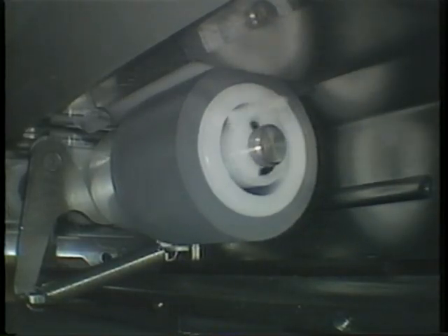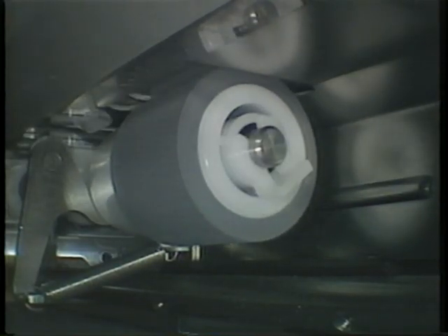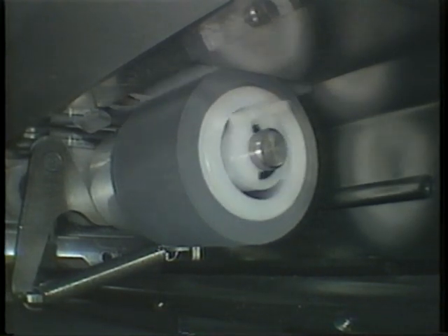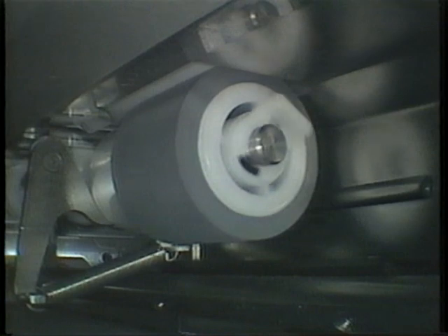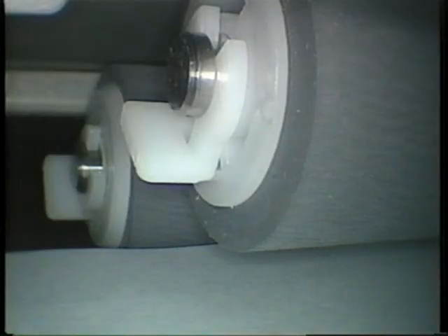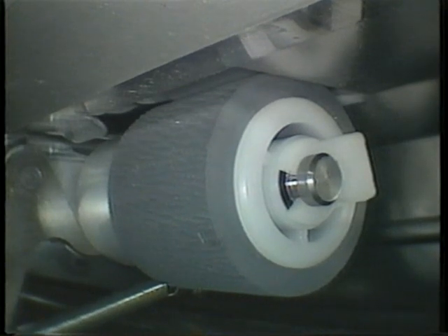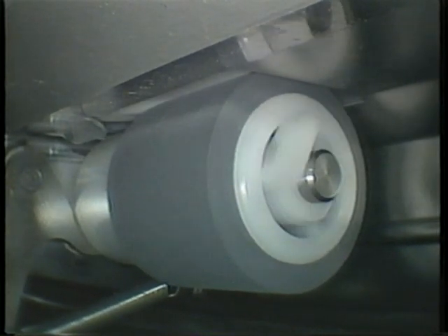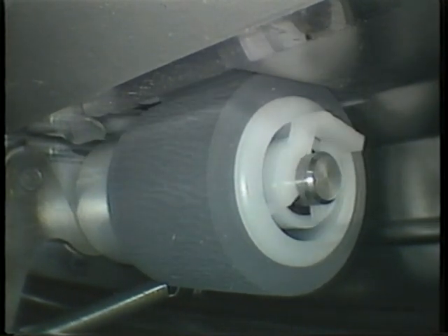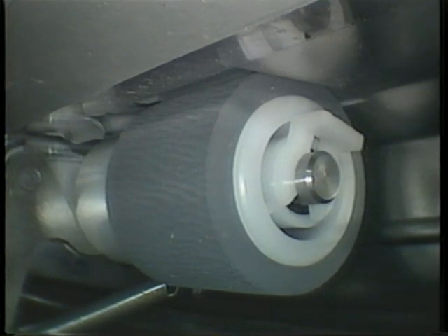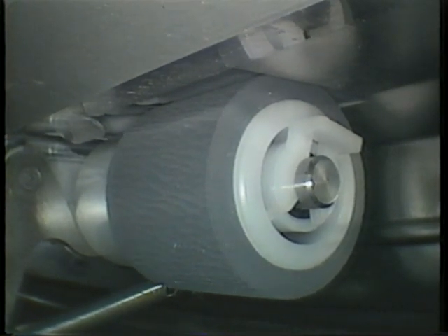If the feed roller picks up a single sheet from the supply, forward rotation is transmitted through the paper to the bottom roller. The clutch releases and the bottom roller turns forward as well. But if two sheets are picked up, the friction between them isn't strong enough to force the bottom roller to rotate forward. It reverses. This action separates the top sheet of paper and prevents the bottom one from feeding.